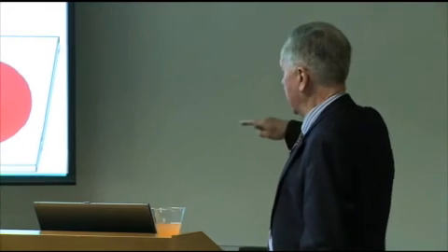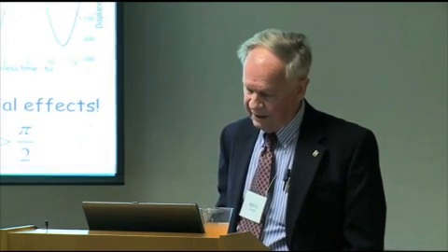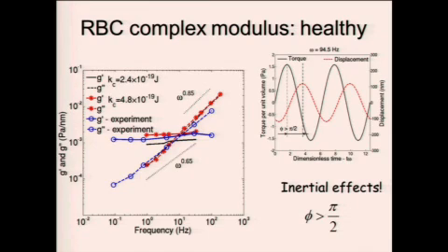If you had a plane half body, engineers do those indentation problems where they press a sphere into a half body, and there's a lot of mathematics, and they get some answers out of it. Well, this geometry is much too complicated to do that with, but when we look at the data, because we know G and G prime independently, if we make one of them agree, then the second one agrees, provided we have the bending modulus reasonably well established. Of course, this is for healthy cells.